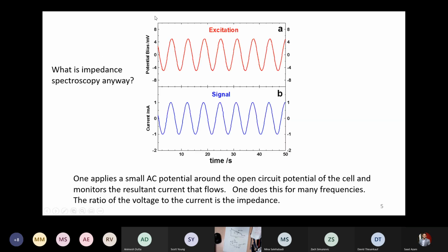So Jeff, question, the EIS technique, is it done at a particular state of charge? You can do it at any state of charge you like of a cell, and you will find that the impedance characteristics of a cell vary with the state of charge.